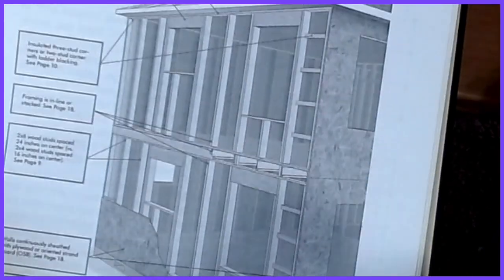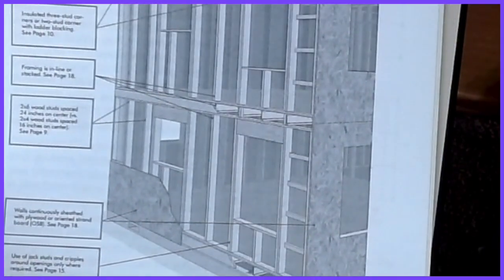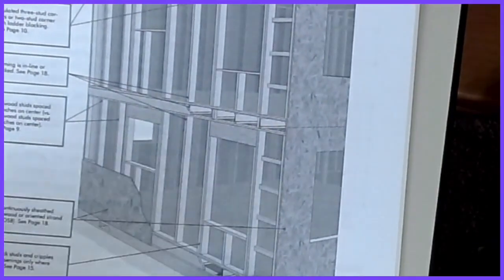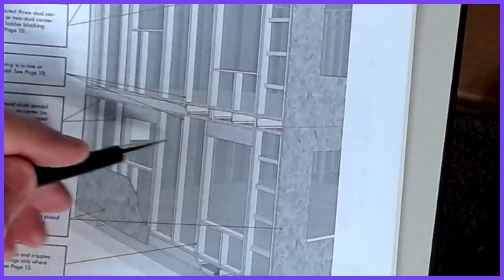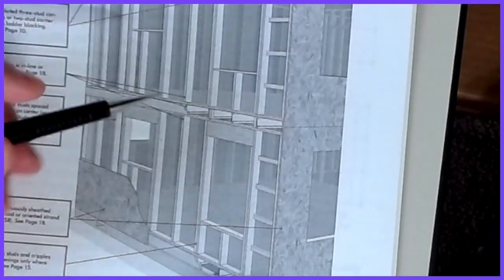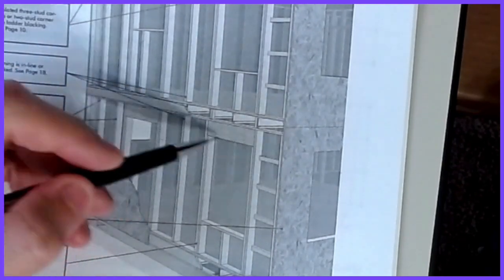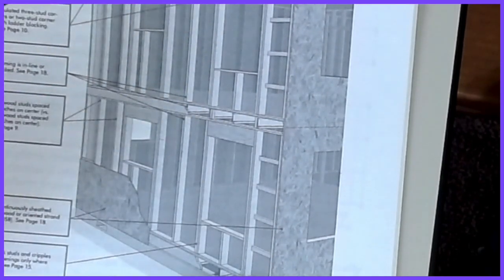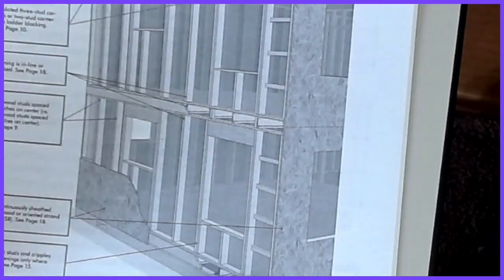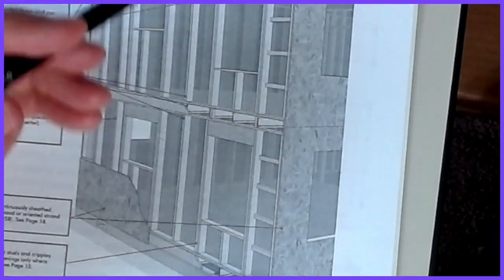Okay, now getting back to some wood construction. This was kind of a graphic that shows, again, this is in your packet, some of the basic construction. Wood construction is a little bit more challenging in that we can't go very long distances without putting another wood member just because these are so lightweight. Normally these are 16 inches on center. But you can see that over openings, they'll put what we call a lintel or a header over the opening, and then this would be where a window goes, and then similarly over a door. I don't see a door on this particular wall, but kind of the sheeting and all of those.